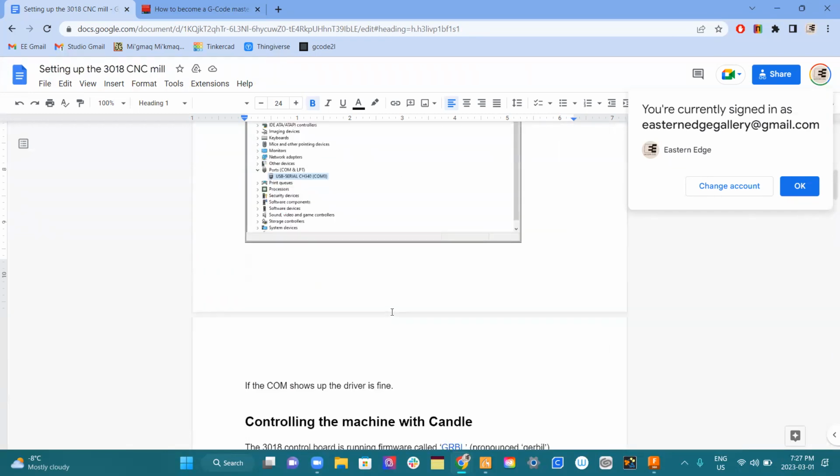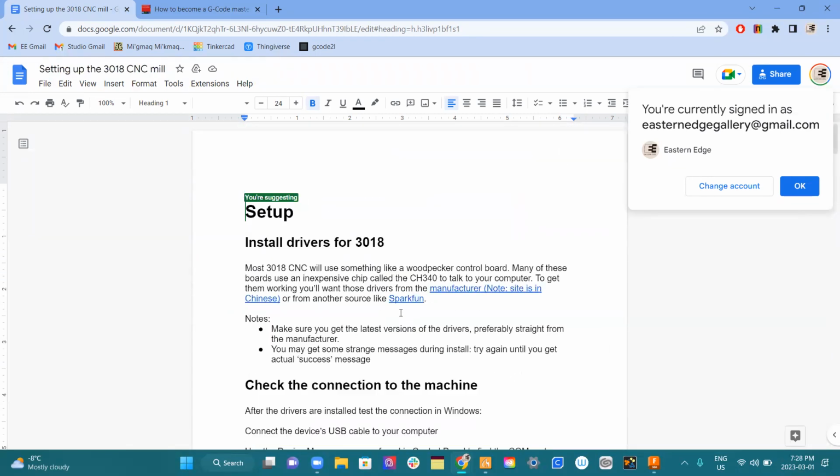This is the instructions for configuring this computer if it got crashed. So this device, like I mentioned, has a gantry. A gantry is a thing that moves in two directions. There's a threaded rod here, and this thing rides on it, and when the motor spins, the rod moves back and forth in this direction. There's another one over here, and then there's a small one that moves up and down. It mainly moves along the table, in a 30 by 18 area. It goes 18 in one direction, 30 in the other, and then up and down.